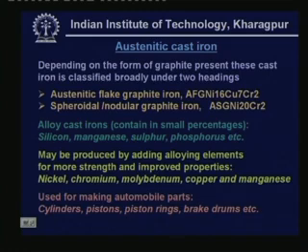All these you can see are well designated by letters taken from their names, for example austenitic flake graphite iron. We consider one of the examples like AFG Ni16 Cu7 Cr2, where Ni is nickel, Cu is copper, and Cr is chromium.